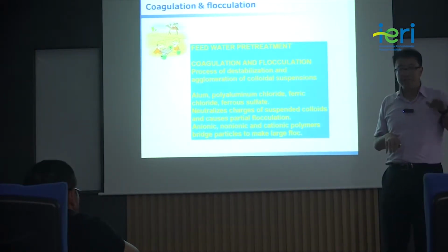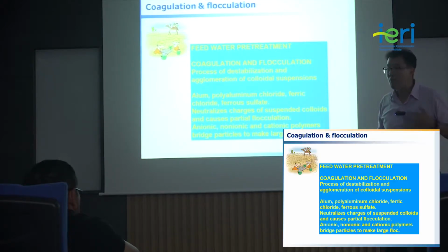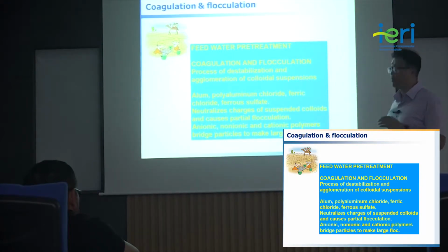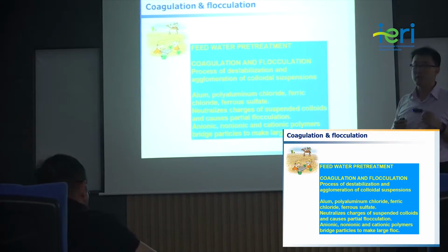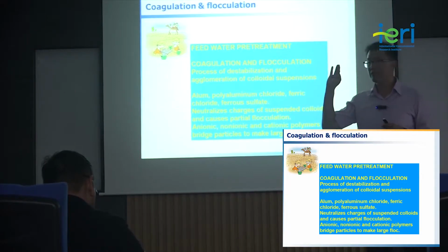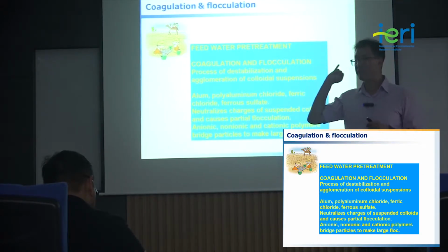To decrease this SDI and get cleaner seawater for reverse osmosis, you can select many unit processes like coagulation, media filtration, flotation, and membrane-based filtration.